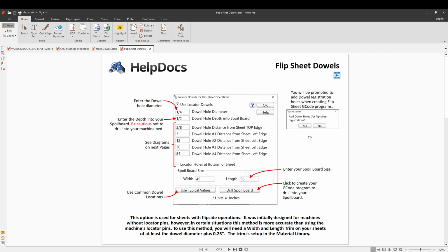We have done this before, but like I said, it's way easier to do whatever you can to avoid flip side operations. Or if you have a rabbet or something and the rabbet and the dado of the face are on opposite sides, just set yourself up with a router bit set and a router that you never change, so that you can do the machining.